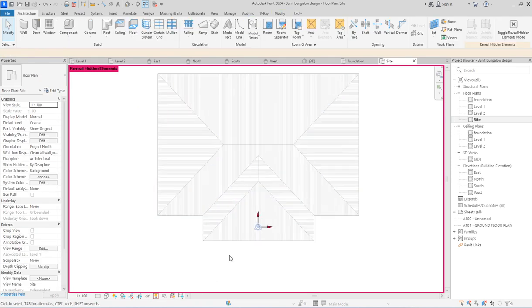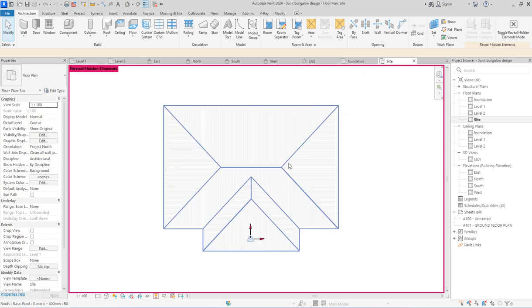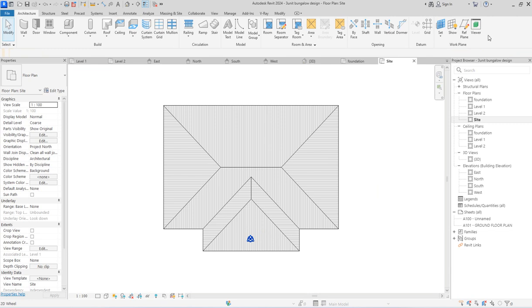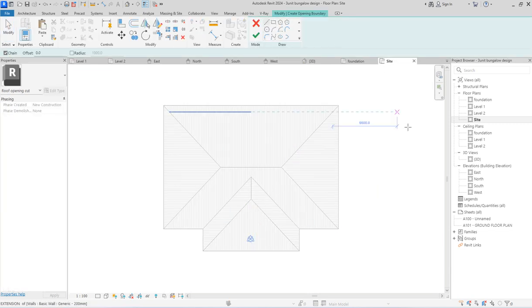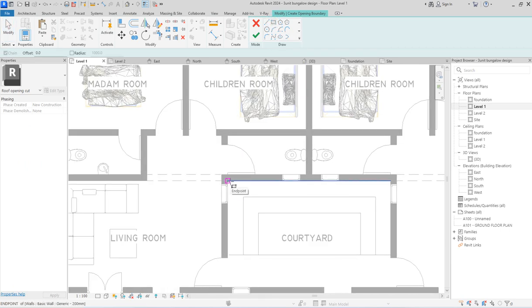So now we want to work on this. We create the whole ridge cap and still have our hole within it. So we start straight up. Click here and say go to vertical again, select the roof at the top, go to the level, foundation level, do as you did in the former one. So select this one. So go to, click on offset of -500. I think that's what we did, -500.